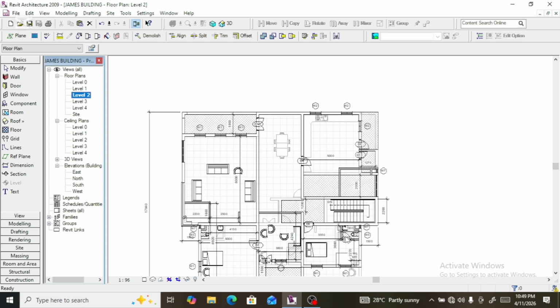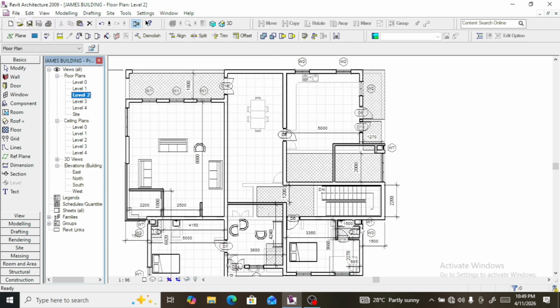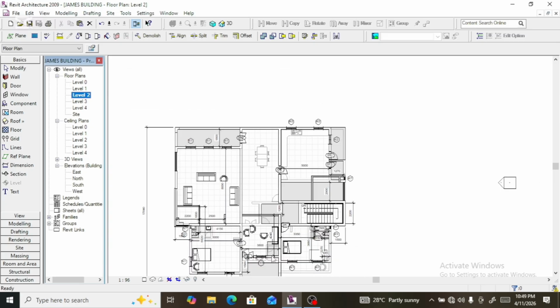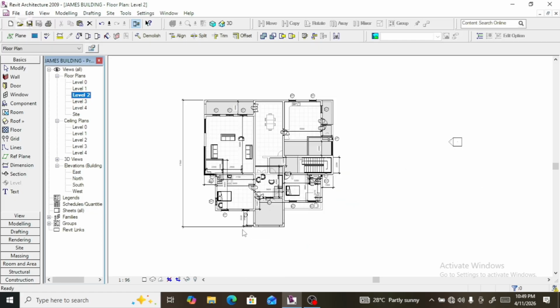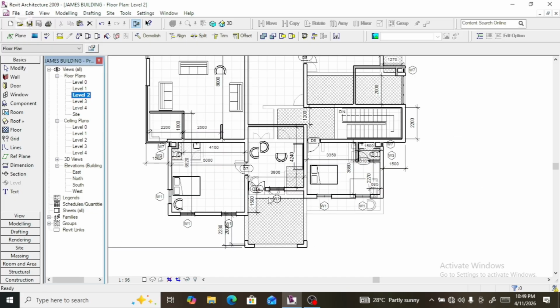That is why we did not place a dot at this front, because it's not going to be useful anymore. The toilet down there can just go below and link into any of the dots around, so that the flow can go to the septic tank. So these are things you have to put into consideration when you're doing your design.